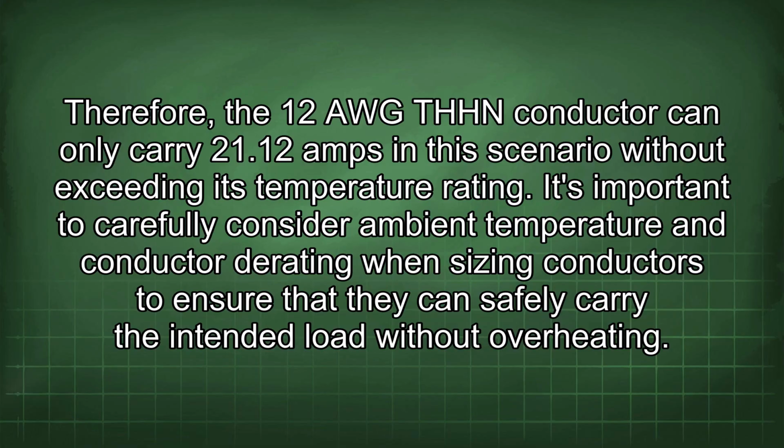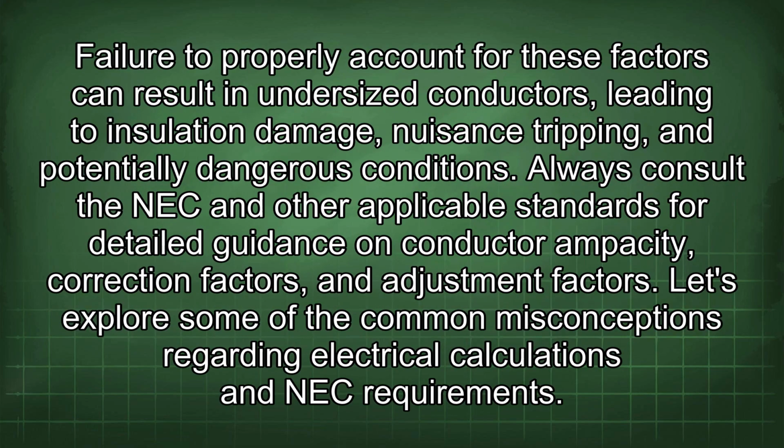It's important to carefully consider ambient temperature and conductor rating when sizing conductors to ensure that they can safely carry the intended load without overheating. Failure to properly account for these factors can result in undersized conductors, leading to insulation damage, nuisance tripping, and potentially dangerous conditions. Always consult the NEC and other applicable standards for detailed guidance on conductor ampacity, correction factors, and adjustment factors. Let's explore some of the common misconceptions regarding electrical calculations and NEC requirements.